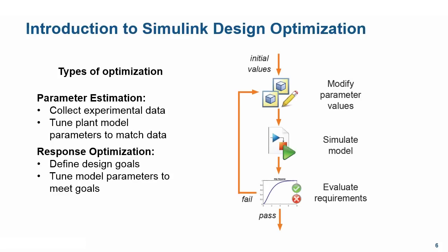The diagram to the right shows how Simulink Design Optimization works. The optimization routine begins by simulating the model with a set of initial values for our design parameters such as the suspension upper arm length. The model outputs are evaluated against user-specified requirements, in our case, the camber angle and the roll center design goals. This produces a cost function which must be minimized. As long as the optimization criteria have not been met, the model parameters are modified based on the optimization routine and simulation is run with new values and the cost function is evaluated again.